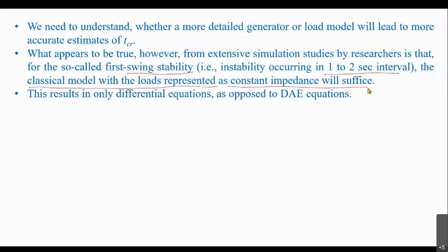So this results in only differential equations as opposed to the DAE. Therefore we don't require the differential algebraic equations here. Instead we can consider only the differential equations, because the classical model is represented by differential equations itself, and we will consider the load as an impedance load.